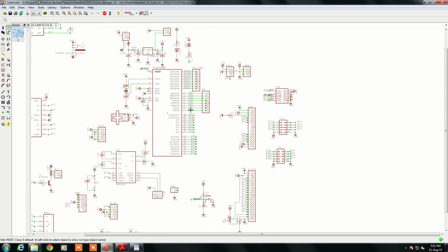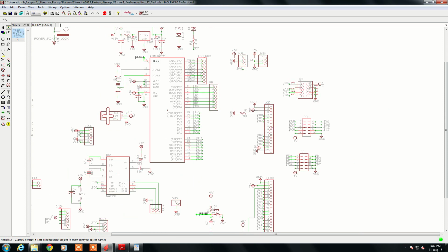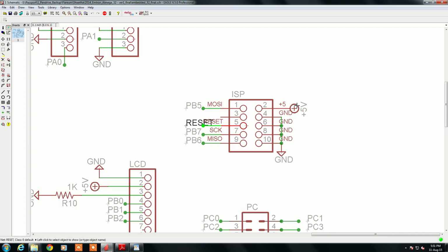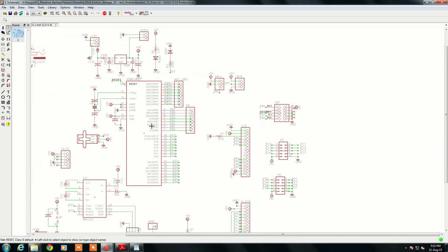So how to program this microcontroller? Since we do not want to remove this controller every time from the board, these programmable signals which are connected to this connector, this is called in-system programming. So there is a 10-pin connector where a programmer, what is called a USB ASP programmer, is available. You can connect it here. So whenever you are using some microcontroller based systems, you should equally worry about how to program the chip without removing it from the target device.